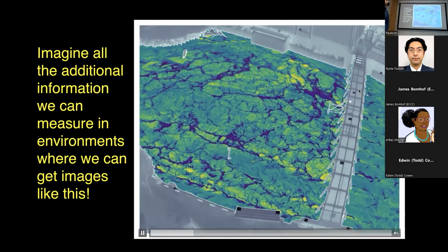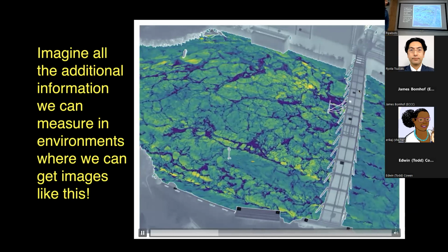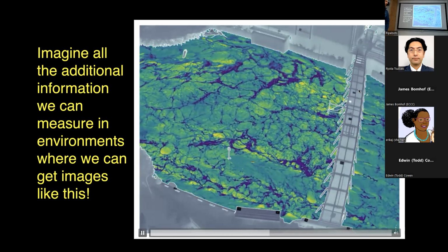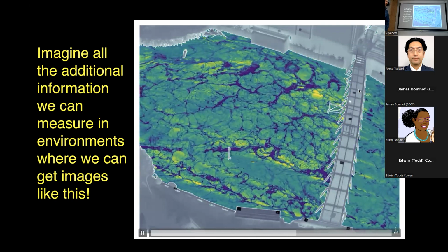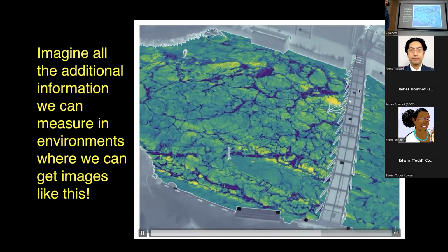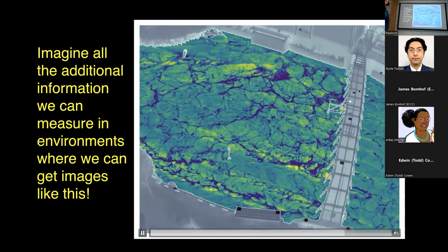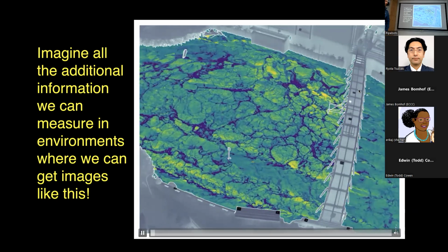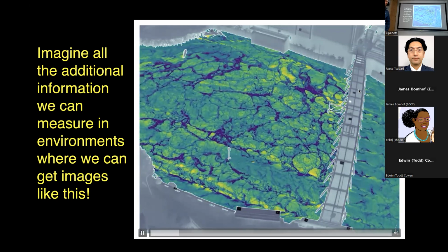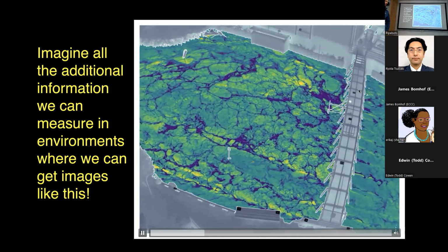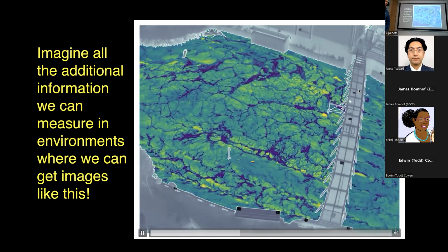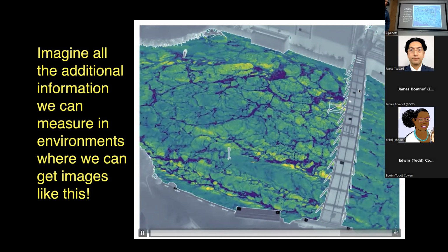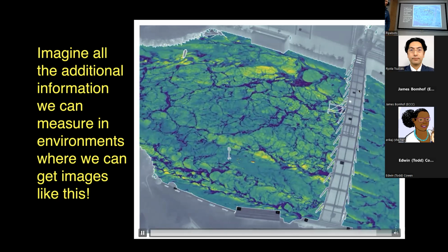And it's really tricky because, of course, acoustic techniques fail there. It's very hard to ground truth these techniques. So I think we will probably have to turn to the lab to understand at least, are we doing okay, where we can measure bulk flow rate by simply, we know how much water we're pumping through a pipe, and we can then create these very aerated flows, particularly at some of our larger facilities in the US. The US Bureau of Reclamation, for instance, has facilities like this, and we have some mountain stream locations that are actually manufactured sites where we know the flow rate. So I think we'd have to start there, but we'll measure something.